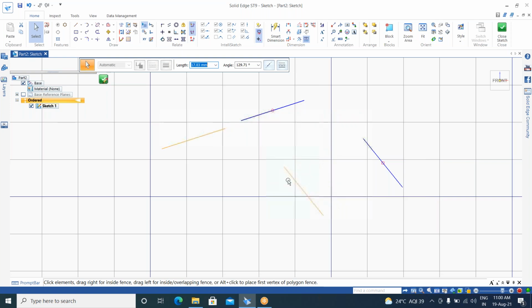I'm moving a single object, but with the moving of the first element, the second element is moved automatically. Why? Because these two are completely rigid with one another, so we cannot move individually. So like this we can apply the rigid set. Up to here I think everything is clear. So draw and relations I have explained.